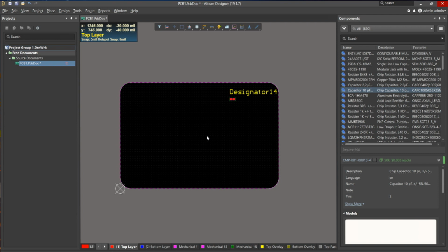So very traditional way of doing it, DXF import. The other traditional method we see using Altium Designer is that we can actually bring the 3D body directly into Altium, and we can define our board shape from that. Is there anybody currently doing that? Okay, there's a few people that are doing that, but for the most part, you just get the DXF and you just run with it, right?